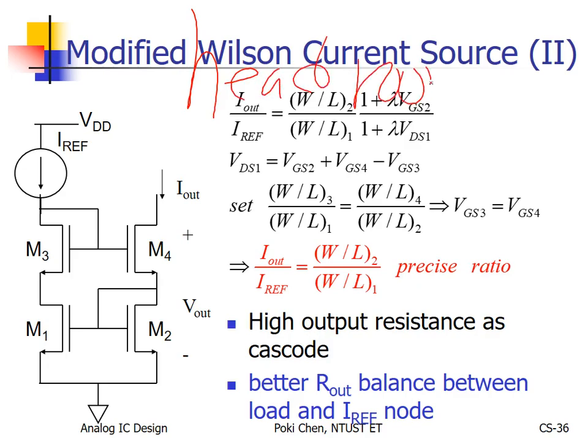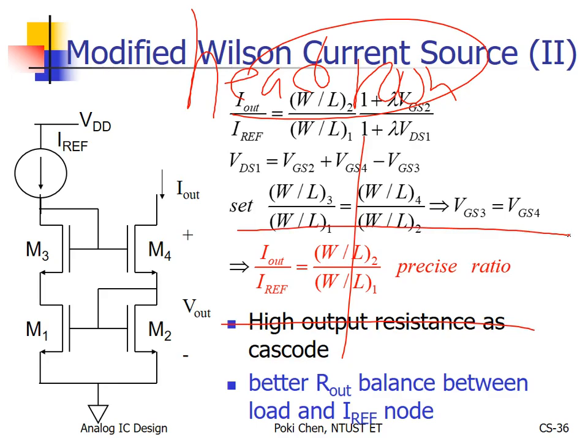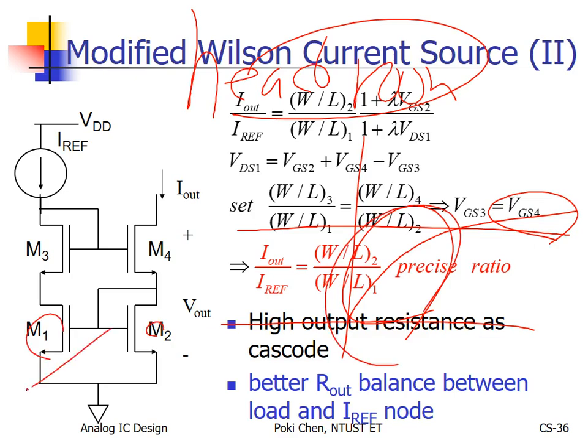tailroom, I told you already. For an ideal current source, it looks like this. But for a practical one, it looks like that. This is the headroom. And that is the not large enough output resistance. How about headroom here? Again, I told you already, for MOS, gate to source needs to be 1 VT plus 1 delta V higher, right? And here is diode connected. So from here to there, another 1 VT, 1 delta V. So you have 2 VT, 2 delta V.